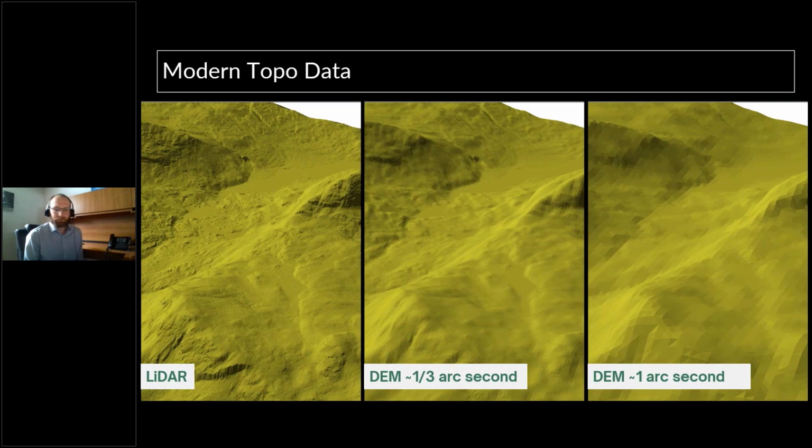Now, if LiDAR data is not a viable solution for you, there are other data types such as photogrammetry derived data or satellite DEM data. And that's still an improvement over an arbitrary line on a map and the sheer will to iron out where to put the road by wandering around in the woods.